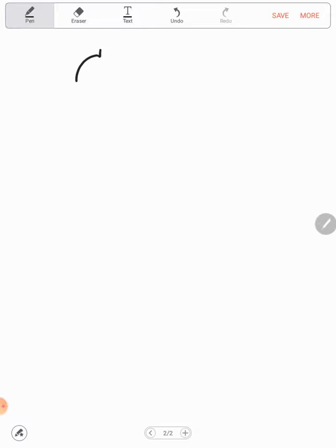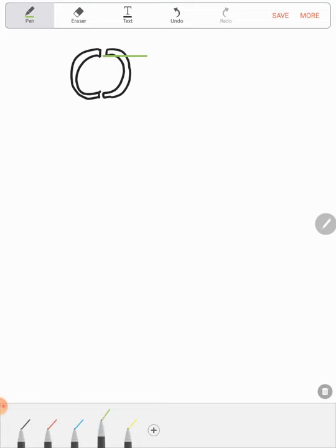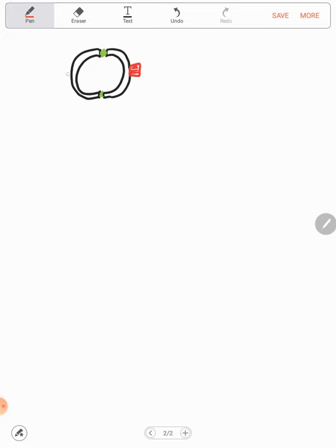So simply, here we're having a simple commutator. Let's assume it only consists of 2 segments. And there will be some insulation between the segments. And here we have brushes. The brushes are there in order to allow the rotor to rotate and in order to allow connection to an external circuit.